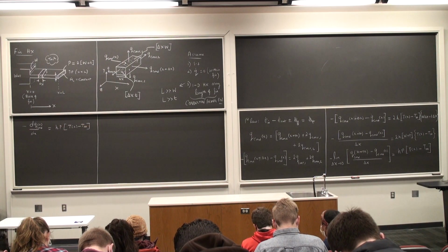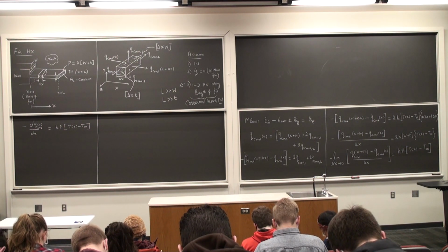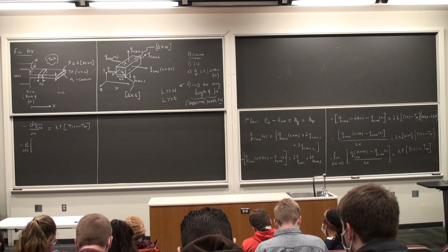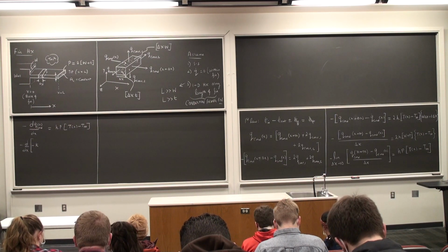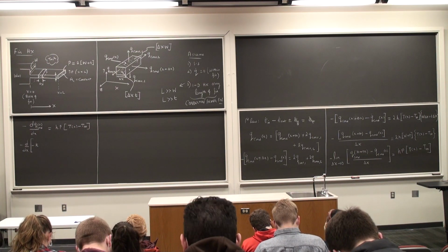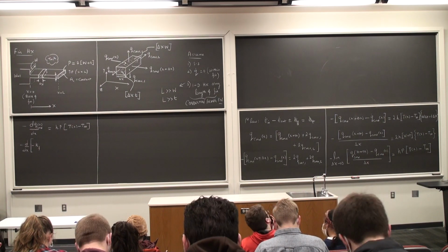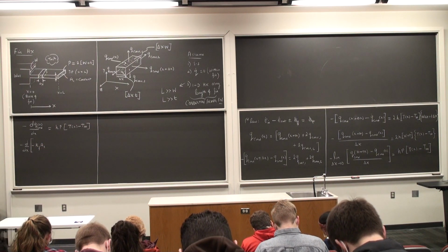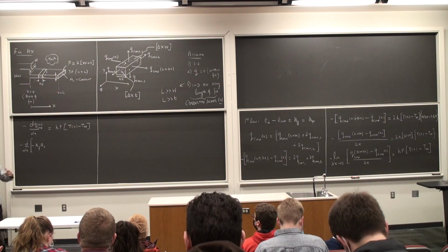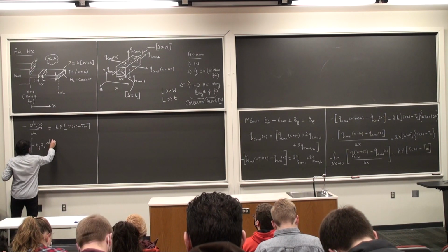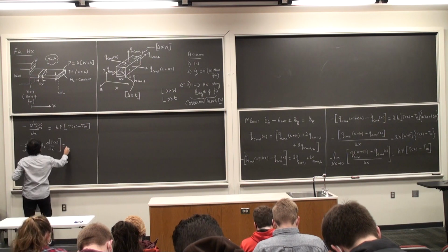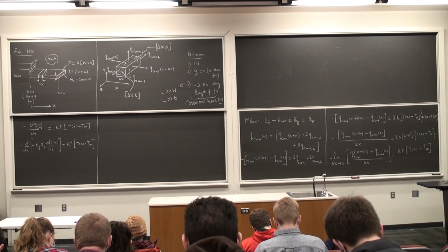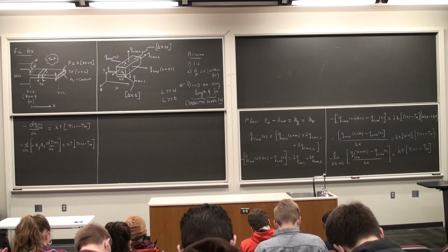Then we invoke Fourier's law. Instead of q conduction, I'm going to write it as minus k times dT by dx. So this is minus d by dx of q conduction, which from Fourier's law is minus k. To differentiate the fact that we have a fin and then we have a plane wall, I'm going to say that this is k suffix f for the fin. This is Fourier's law applied within the fin. And this is going to be the area of cross section, which we had labeled there, which is a constant for us. The thermal conductivity is also a constant for us in most of our calculations. Is h times P times T of x minus T infinity. And magically this negative sign disappears.